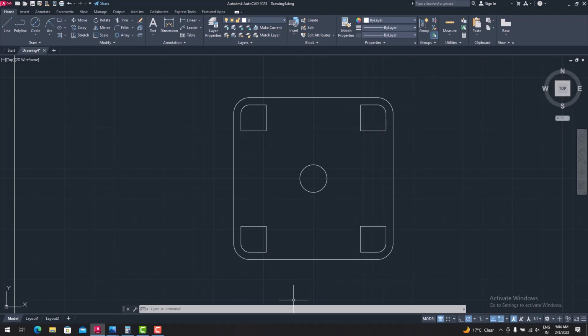Okay, you can also do this by using the mirror method, like selecting this object, then specifying the mirror line by selecting the 2 points. Then this figure will come. After that, make this figure the source and stretch a line from here to make the mirror line, and do this.